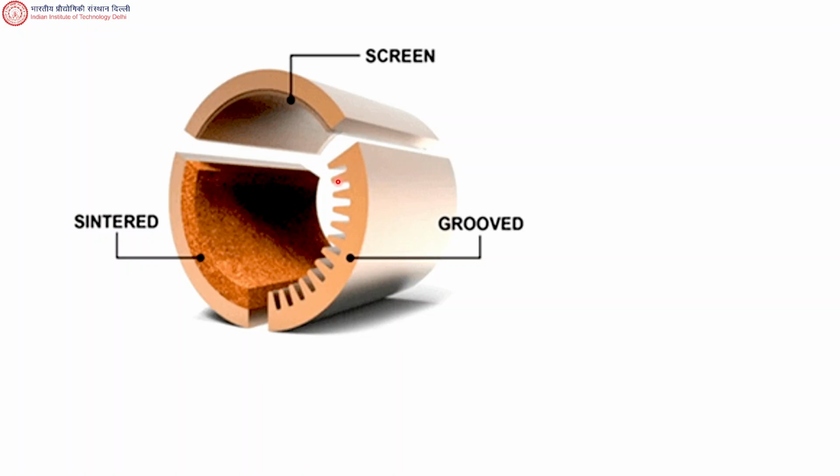This is because of some kind of fluid mechanics action. What do you call it? Capillary action. So this is the capillary effect. The wick provides capillary structures, and because of that you get the capillary effect and the liquid gets pumped. The liquid actually is getting pumped.